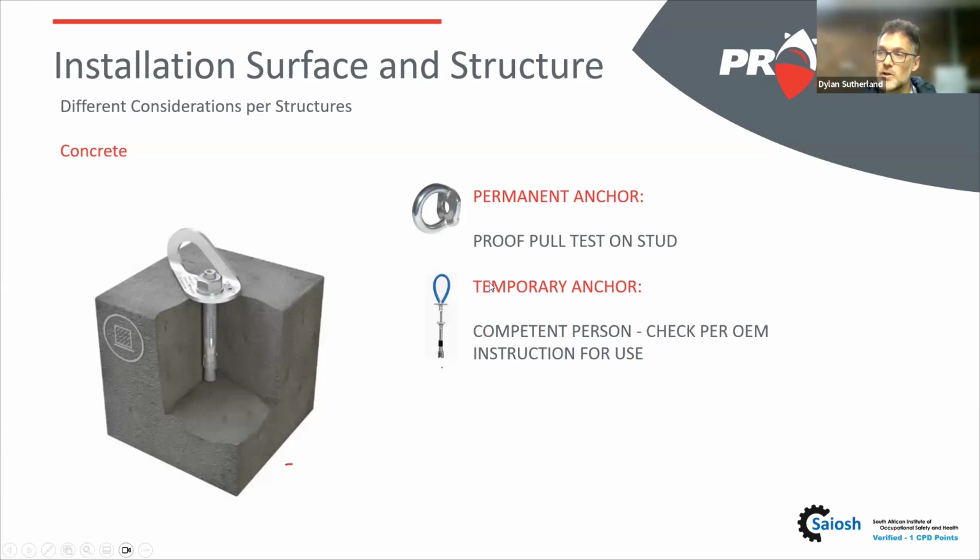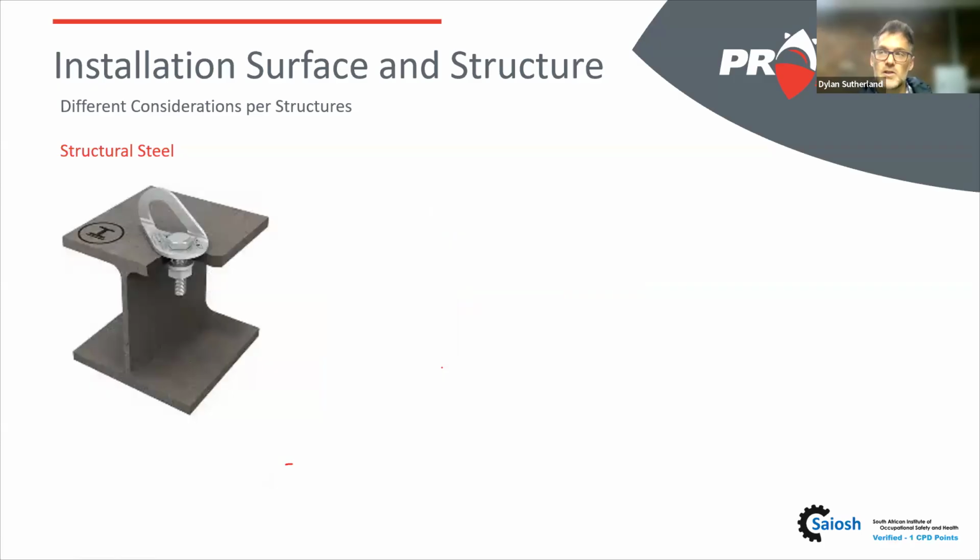The other thing we can do is we can also use temporary anchor points into concrete. But this, I need to emphasize, you need to make sure that you are referring to the OEM's instructions for use, because that will talk about the competency of the person. That will talk about the checks to make sure that it's actually going to work as intended. But these would be two considerations you could use when working with concrete. We then move to steel.